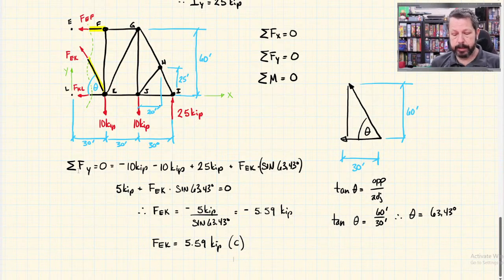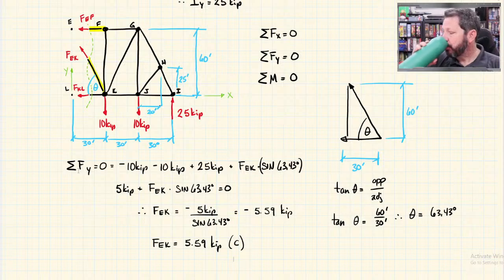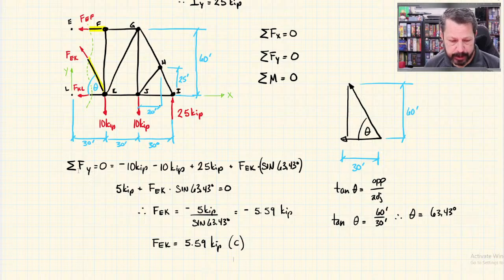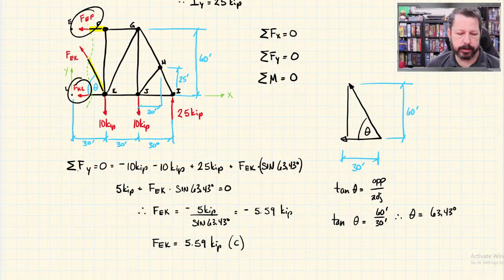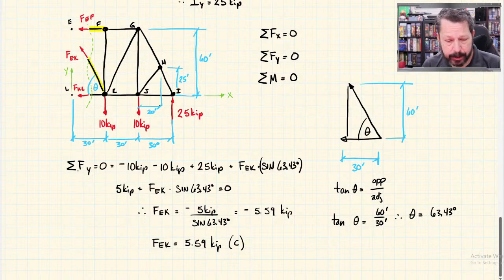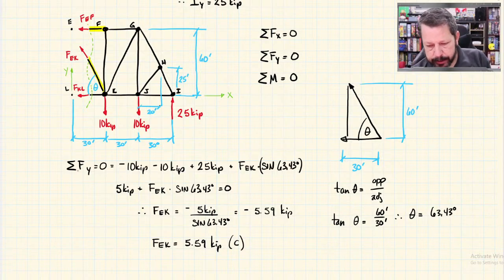So now I've got a new thing though. I could go back to the forces in the X direction, but I'd still have two unknowns in one equation, so that wouldn't work. I've already written the Y equation, so that leaves me with the moment equation. When you're dealing with the moment equation, normally if you're doing method of sections, you have three unknowns. Actually, we only have two unknowns now because I solved for one of them, but you want to solve for one of those.